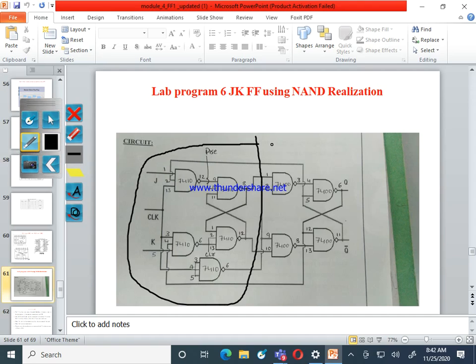I am taking 2 NAND gate ICs of 7410. In the first IC, I am realizing J, K and preset, because only 3 is possible. Because of that, I am taking a second IC of 7410. There I am realizing clear and the NOT gate. All the 3-input NAND gates are over. Actually, one is left out there because it is unused. I don't have any other 3-input NAND gate in the diagram. Only 5 are there, and I have already done them with 2 ICs.